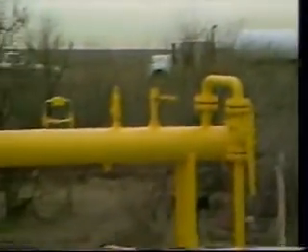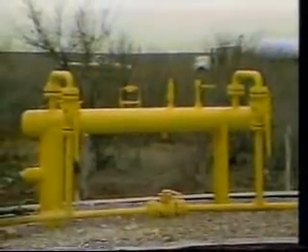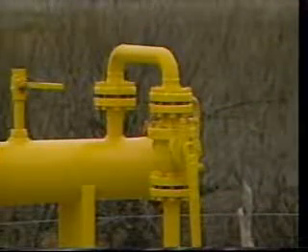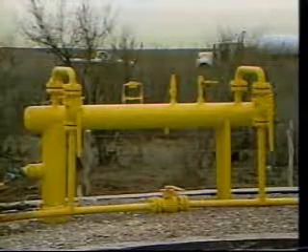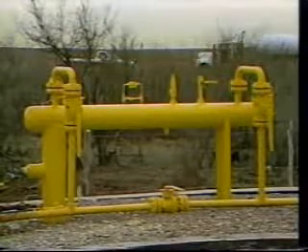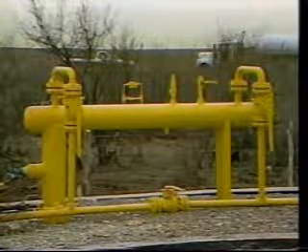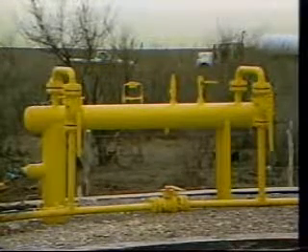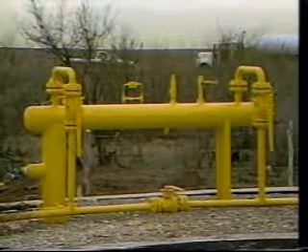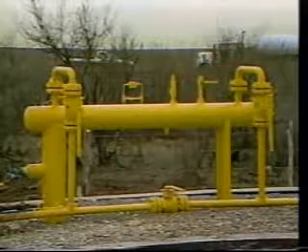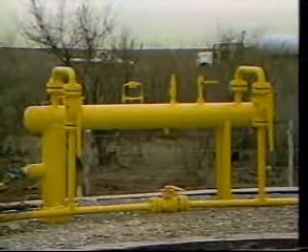The purpose of a drip is to remove any entrained liquids that may remain in the gas before it enters the pipeline. The gas enters on the right at the top of a horizontal piece of pipe. It moves along this pipe and the liquids drop out. The gas then comes out of the pipe on the left-hand side, and any liquids drop down into the vertical section of pipe on the left-hand side of the drip. From time to time, the liquids then are collected and disposed of.